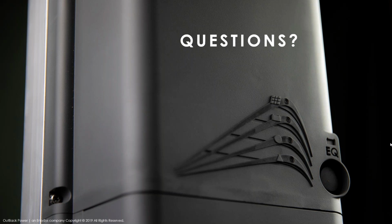Fortunately, FM100 has a much more robust DC to DC converter. And what that means is the highest amperage that will ever come out of the FM100, we've tested it, at 9,000 watts, 10,000 watts of PV input, the highest amperage that will ever come out of it is about 101 amps or 102 amps. And even that is only very momentary in excess of 100 amps. So in all of our testing, we identified that issue with the FM80, so we've tested the heck out of that with the FM100, and we have not been able to cause any nuisance tripping on appropriately sized 125 amp output breakers.